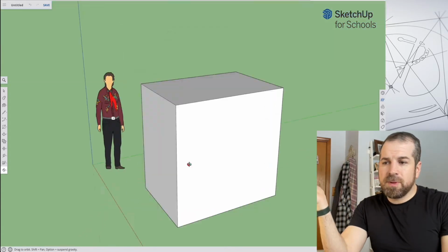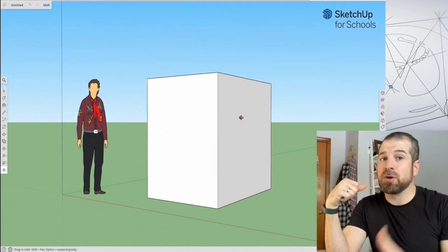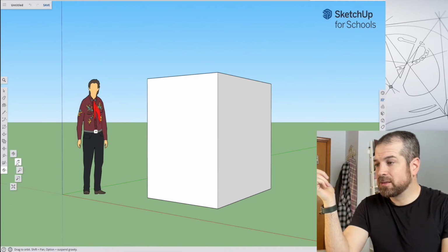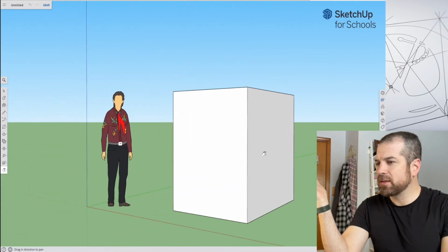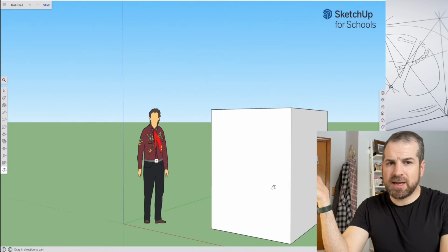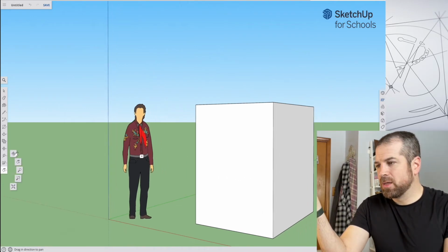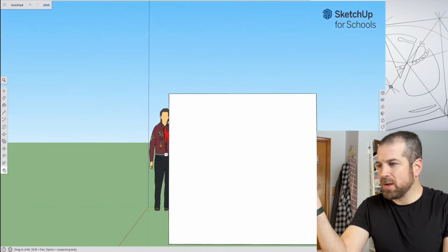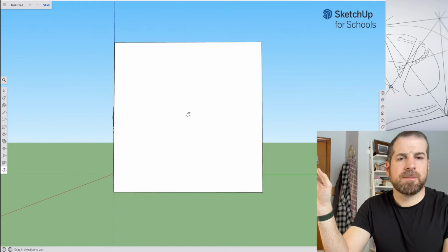So again, orbit moves around like this, and this is more like your head movement, like with your right thumbstick, and the pan, which is the hand, is more just linear movement. You click and drag, click and drag. You are just moving linearly. So say I wanted to see this side of it, I go right here, and I wanted to center it. Then I would take my pan tool and I would click and drag until I centered it. And there you go.